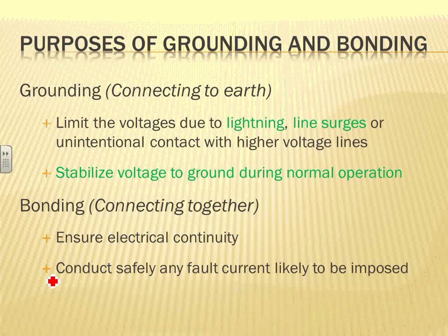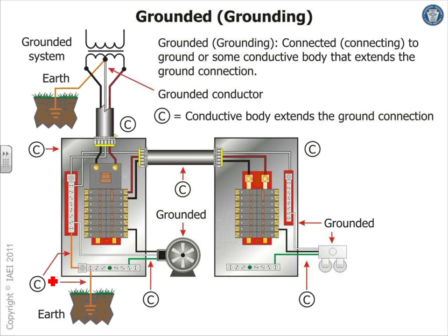You don't have to trip. If you have an impedance grounded system, you can control this so you don't trip. You monitor it, you control it, you don't trip. And if there's any surge in the system, you absorb it through that impedance. So that's a couple of things.